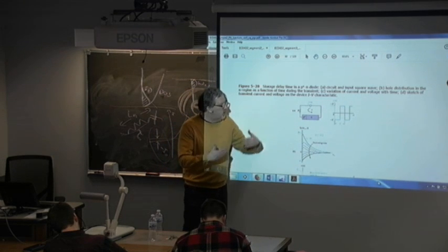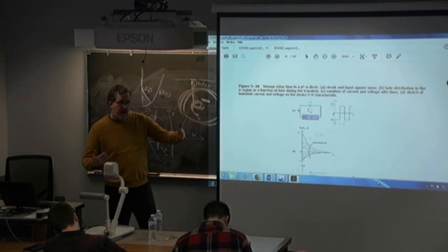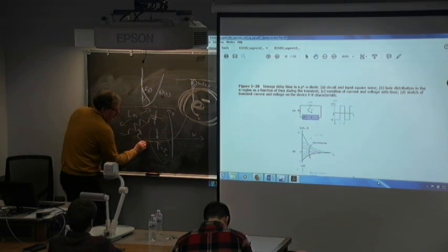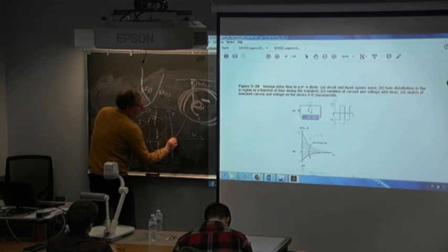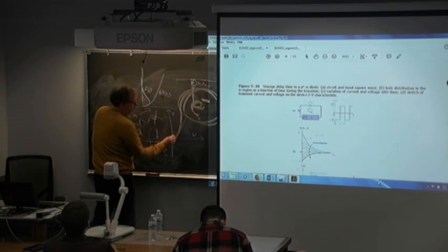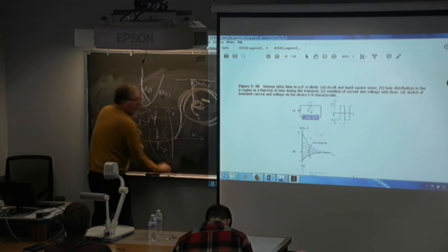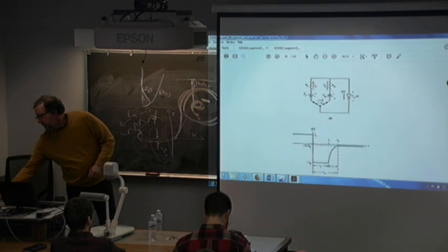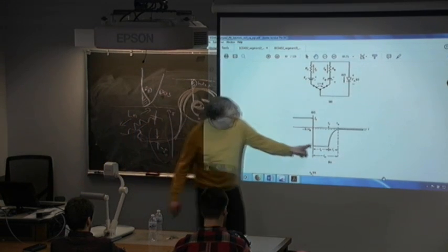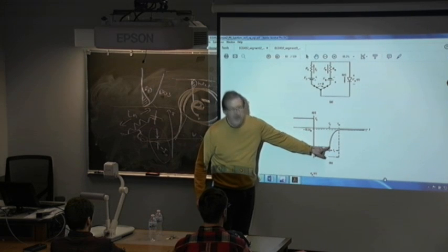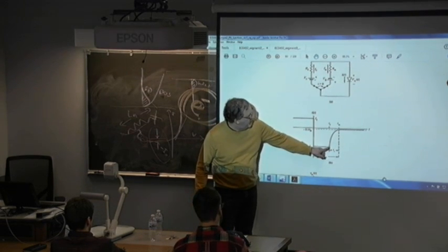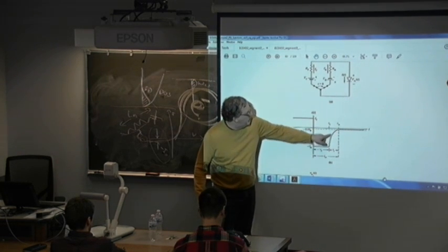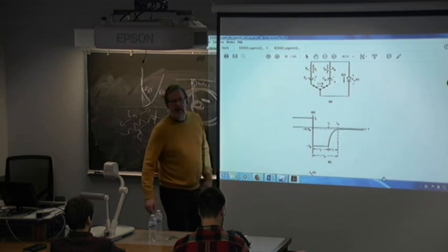And only under reverse bias can it drop a large amount of voltage in the Kirchhoff voltage loop, right? Because a diode in reverse bias can drop a lot of voltage, but under forward bias, it doesn't because the current is going up exponentially. It doesn't get very far. So it's stuck in forward bias, and at this particular point, it finally hits equilibrium, and then from here it goes from equilibrium to reverse. So the exponential is concave down in this way rather than concave up that you might expect.